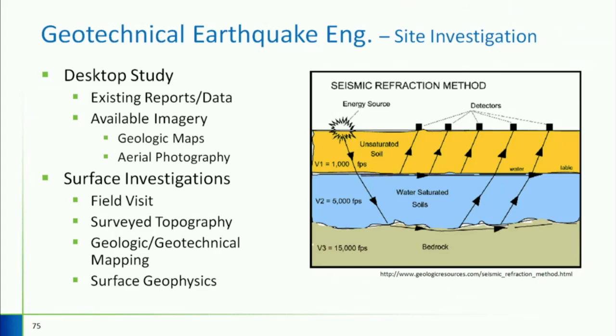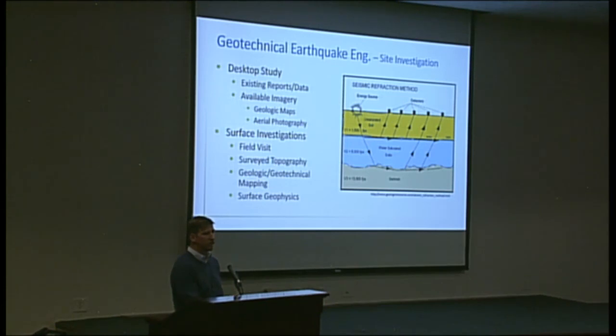One of these surface techniques is a seismic refraction, where you put all these geophones, detectors, on the surface, and you usually put like a metal rod and hammer it. And then you measure the response, and you can get these distributions of waves. So the idea here is that this wave that comes here, it's going faster on the bottom than this one is right here. And eventually, it's going to come sooner to this location because it's traveling faster. Even though it goes farther, at some point, it will come there sooner, and you can get the distribution of layers this way.